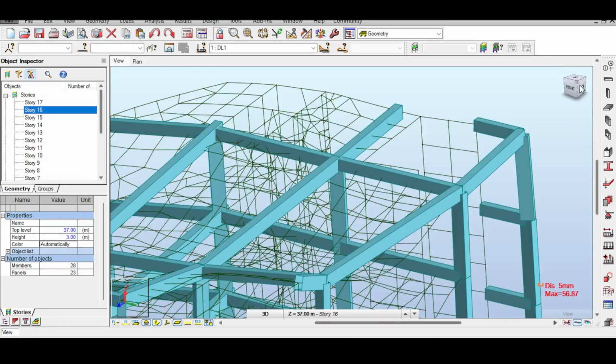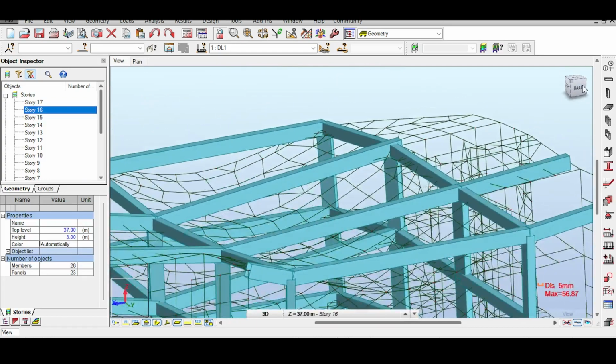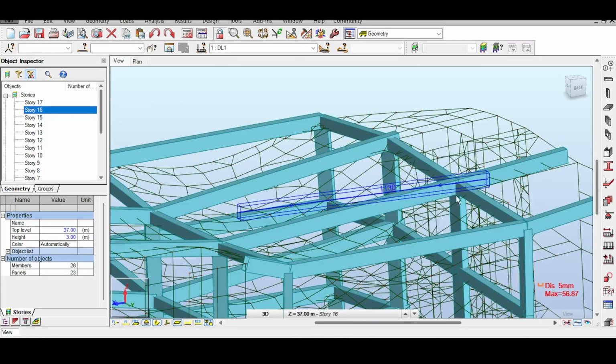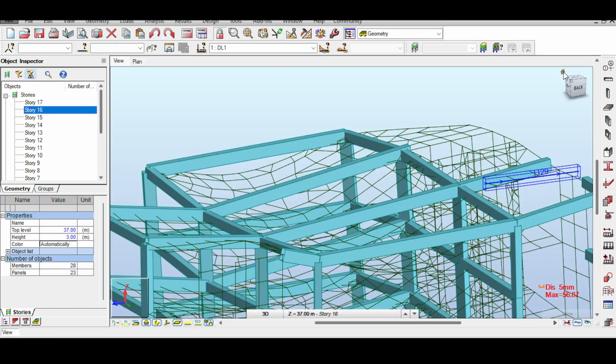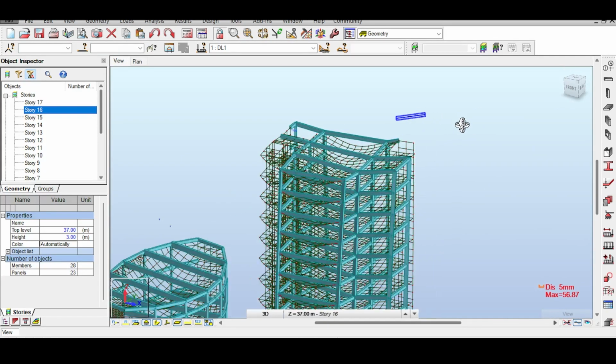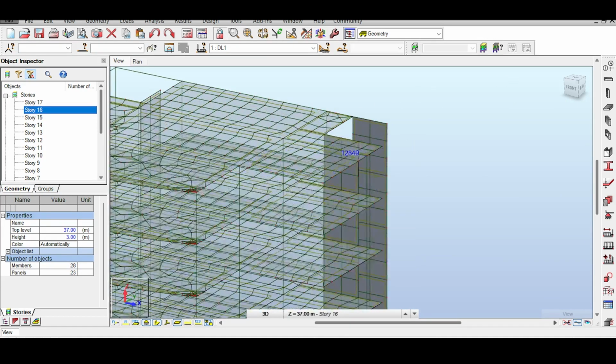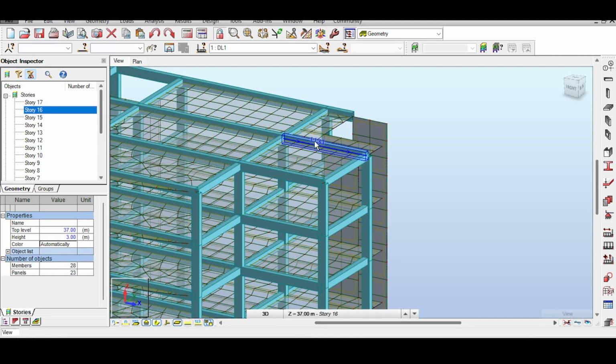so that's a good thing. And the issue that actually uncovered this error was that the beam here was disconnected from the column, something that should not be. So now it's not disconnected, so now I can live in peace. Now I still have the twisting and torquing of that structure to deal with. So okay, I'll just now select both beams, and now I'll do some copying. So I'll just select that.